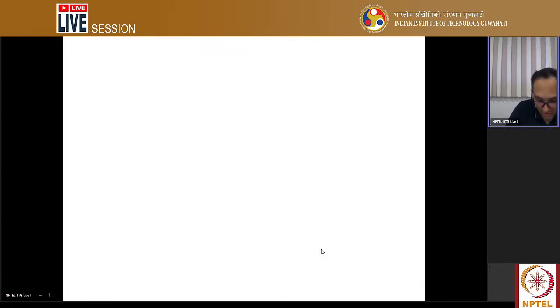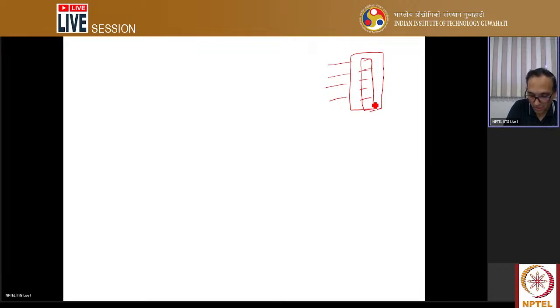So what I mean is that if you see the problem of LUT mapping, in a LUT what you have basically is a memory, right? A ROM. It can be a single bit. Say suppose it's a 4 input, right? A, B, C, D, 4 inputs. Then there are 16 locations, 0 to 15. And now you have A, B, C, D, 4 inputs, so these 4 inputs act as the address for this memory, right? And what do you store here?